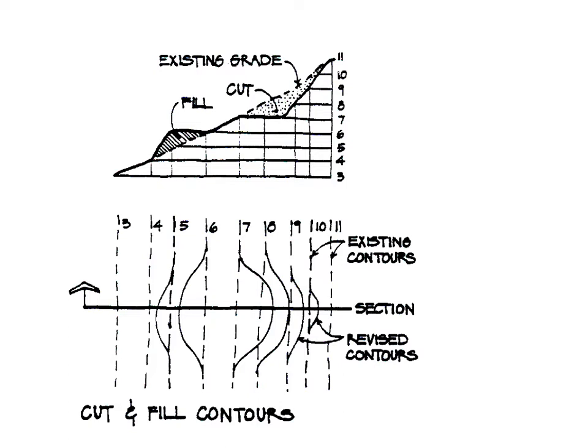And so you can see here that in this plan there's a desire to create a couple of flat areas, and in order to do that, on the right it's a cut, and on the left it's a fill. So you create two flat areas, which might be a yard or a building platform or a path or something. And then if you look down below in the topo plans, you can see how the existing dashed contour lines have these solid lines coming off them, which are the proposed lines. So just, again, familiarize yourself with these conventions.